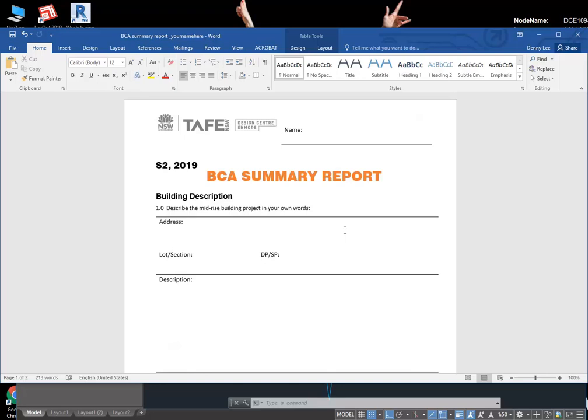If they're timber, you'd have to fire rate them. The floors, mine are concrete. Yeah, concrete's simple, and easier to draw. It's easier in every way except when you go to build it, because getting concrete into a building like this is painful. In here, when I put general floor area limitation, I'm just going to allow for the concrete floor. And actually, it is already concrete, so you could just say you're going to reuse the existing structure.